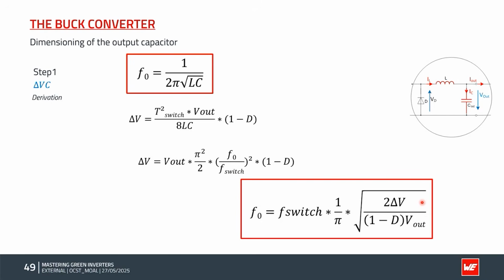So now there's always a relationship between F0 and F switch. We usually say good to cut off a 1/5 or a 1/10 below the switching frequency as the usual rule of thumb. So we will see how that works out on the next few slides. So let's move on to the next slide, please, Andrea.